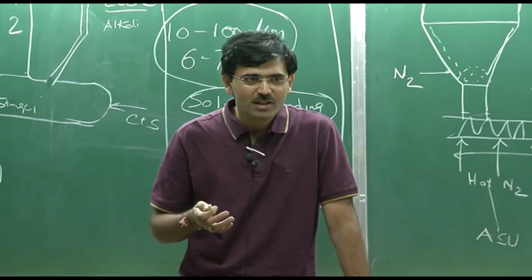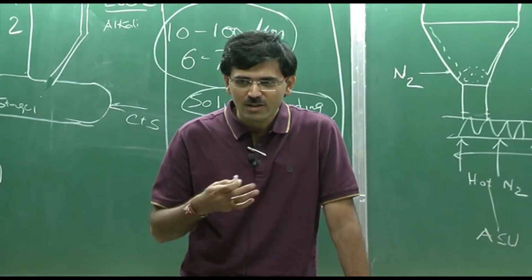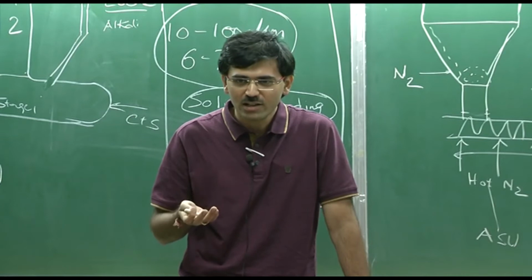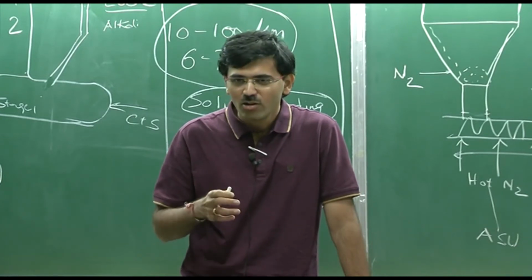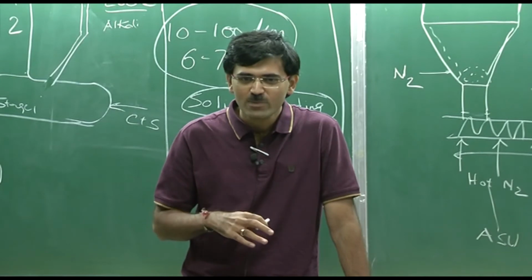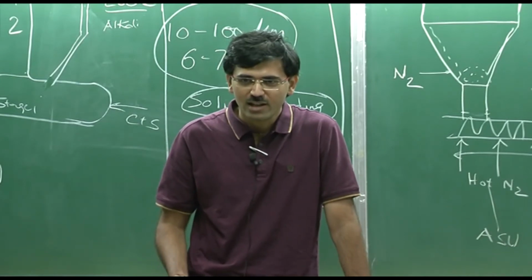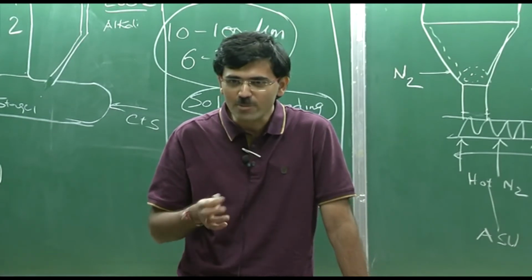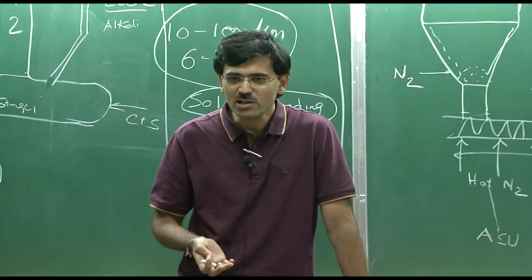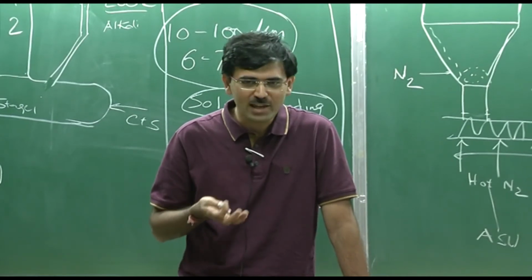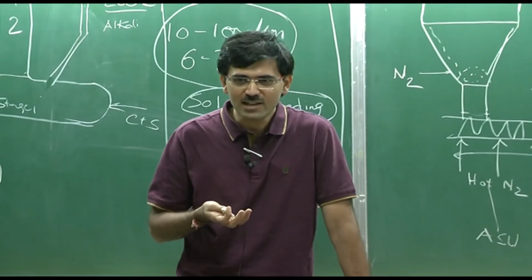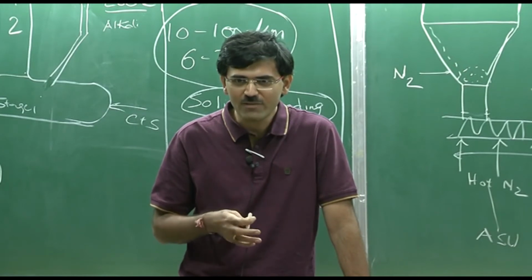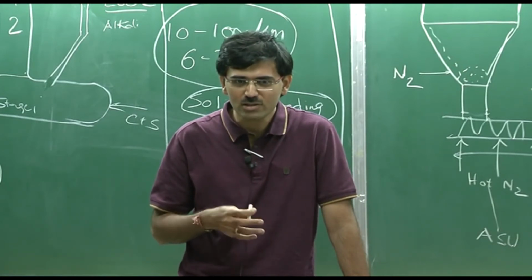For a membrane, the gas transfer is a function of the relative concentration of carbon dioxide on either side of the membrane, right? So the idea was how the carbon dioxide proportion in the flue gas can be raised. To raise it, exhaust gas recirculation, EGR, has been practiced and is very well understood, and the same thing was attempted here.